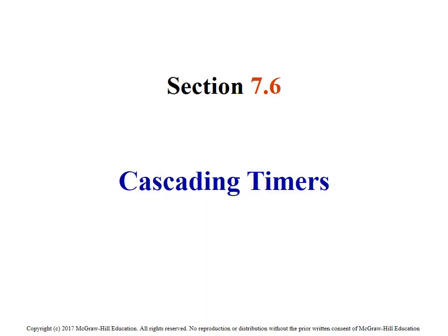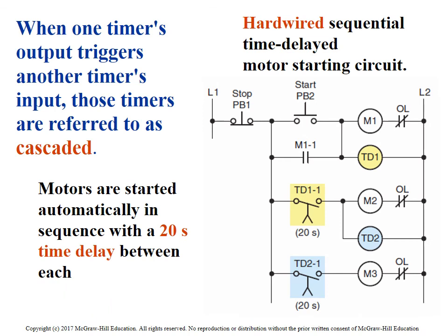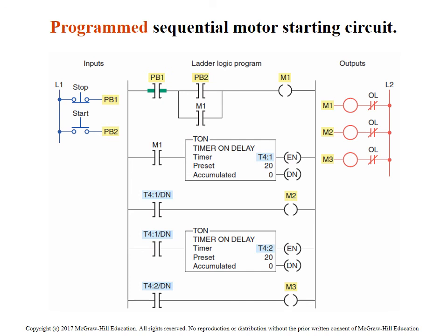Okay, moving along. Cascading timers. Cascading timers is something that I've used quite a bit as well, where you have one timer time out to time another timer, to time another timer, so you can go for a longer length. With the 32-bit format that the new 5000 offers, not so much of a need for cascading anymore. But back in the 500 days when there was not as big a number we could put into a timer, it was more of an issue. So I don't think you'll see too many cascading applications anymore.